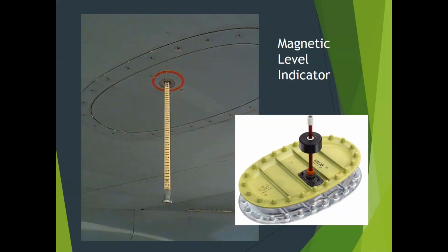So fuel, last time we left off, we finished up measurement, automatic level measurement. When our automatic system isn't working, we have a backup system that can be used on the ground to get an initial fuel level. So a ground crew would get an initial fuel level, and then the crew would monitor fuel flow in flight to essentially subtract from that.